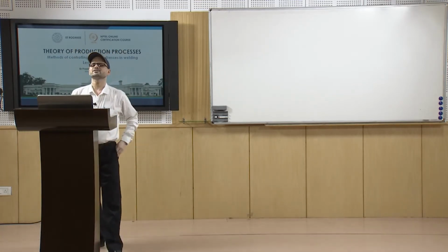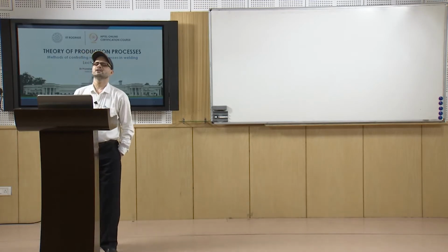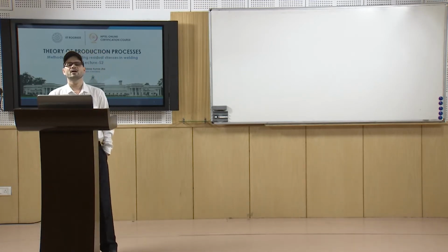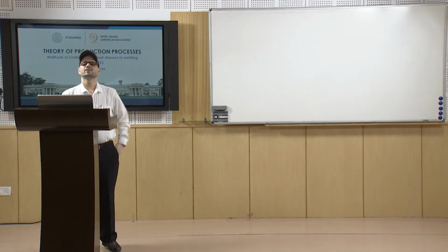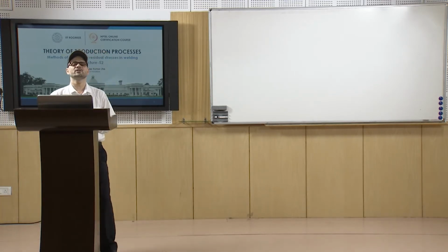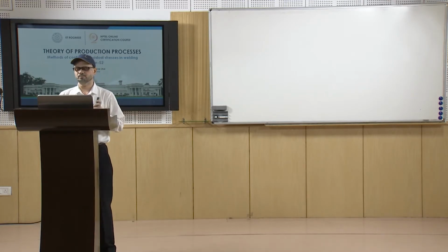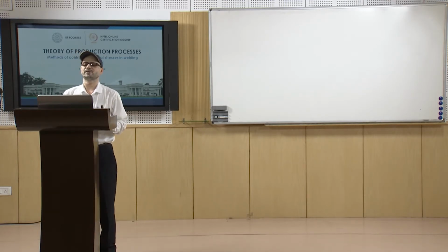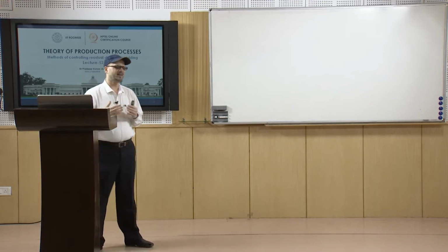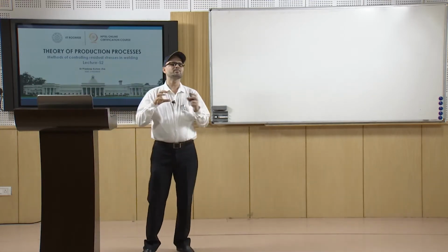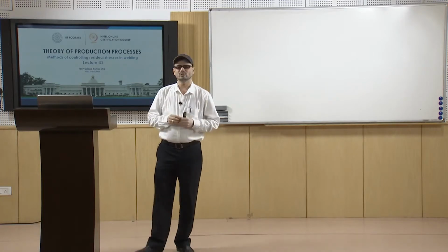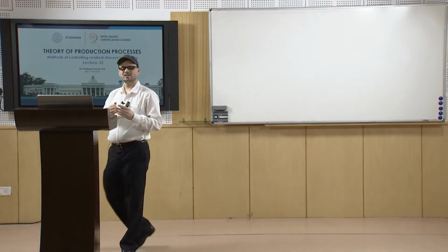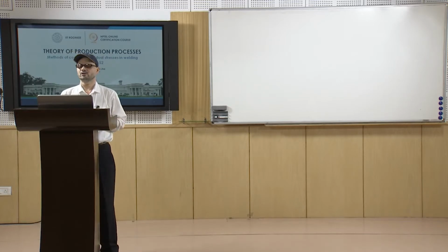Then the percentage relief of the welding stress is dependent on the type and composition, or the yield strength, of the steel. So, when we talk about the thermal treatment, there are many factors: what temperature you are using for heating, how long you are holding, and then the cooling, which is done uniformly.